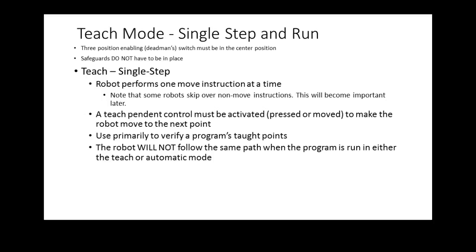And then what would you have to do? You're about to release one of those keys, look it up in your manual, and then press it again. And when you press it again, it's going to do 1 program step, and then it's going to stop. So you'll constantly have to let that thing off during steps, so you can let go of the teach pendant.